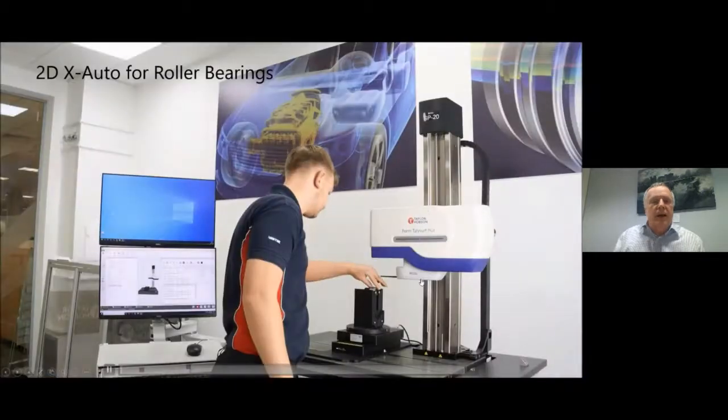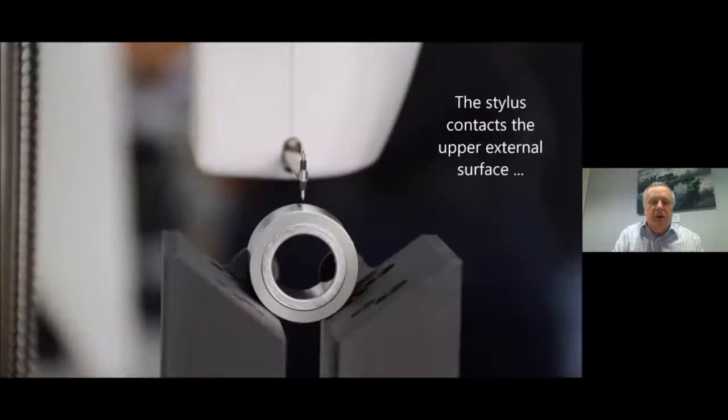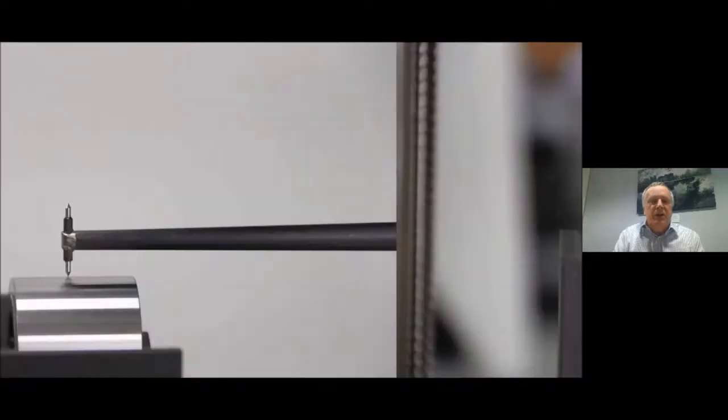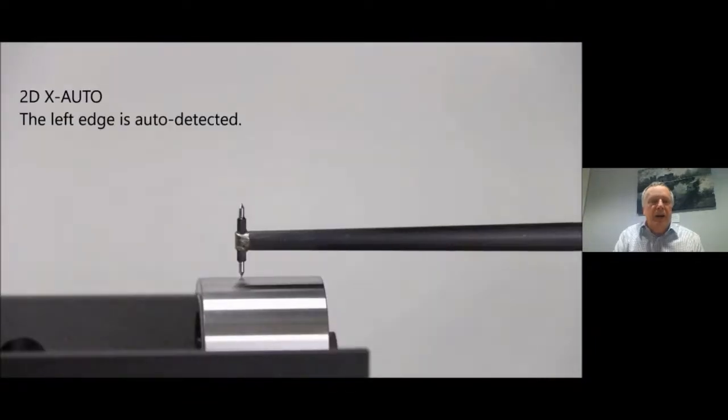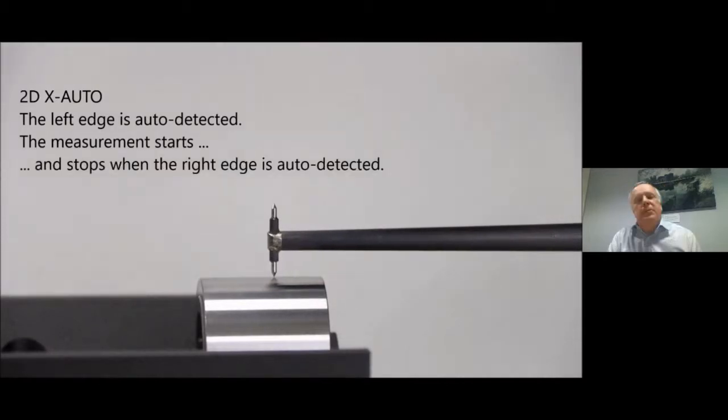And my colleague here has just contacted onto the center of the roller bearing, and the left edge is auto detected. The stylus moves in reverse, just finding that edge there. The measurement starts. And it stops when the right hand edge is auto detected.